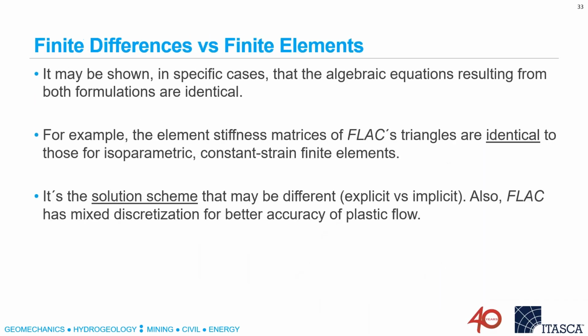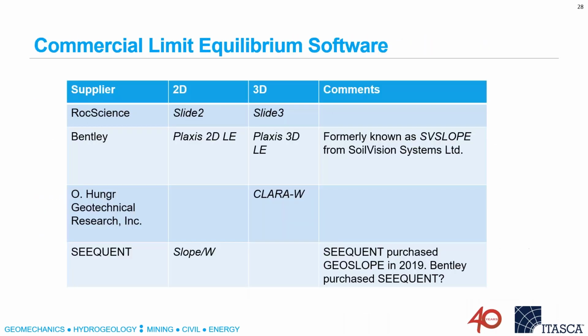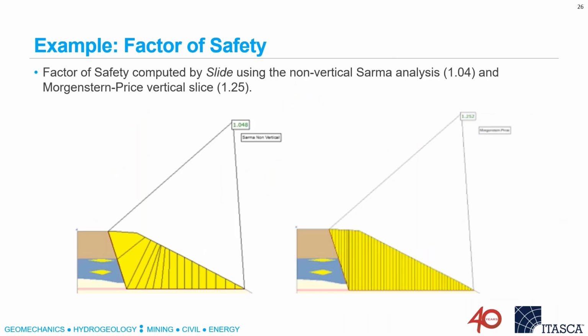is where we have these internal deformations. There it becomes a little bit more important. So in this particular case, where we have internal deformations, we try to capture that dilation, because if we assume it's zero, for example, which is perfectly fine, but it's conservative, because most materials do have some dilation, except for maybe clay.